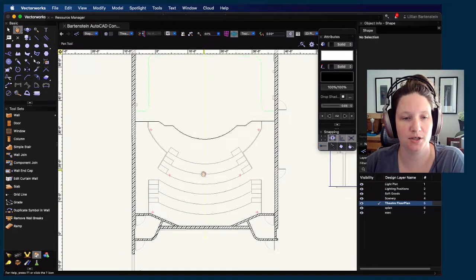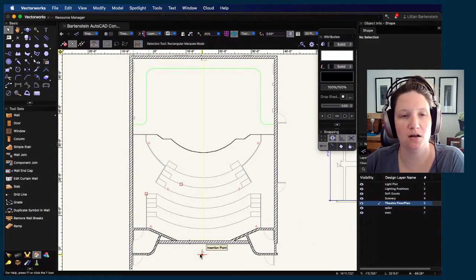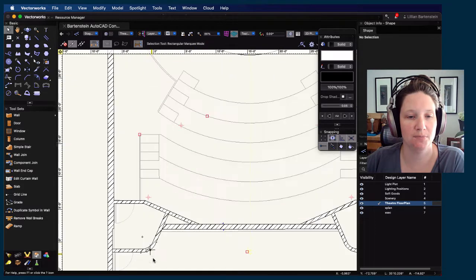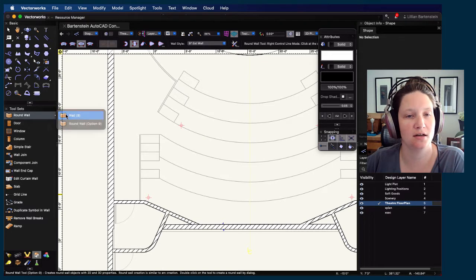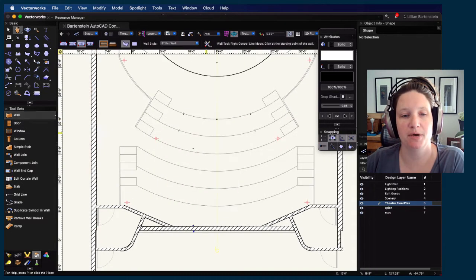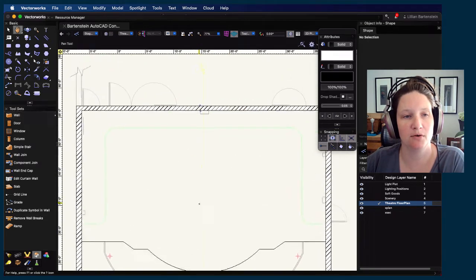Okay, so here we are. I've done all of my little walls. Pro tip, this little bit is the round wall tool, right? Just a quick note, mine is hiding right there under the wall tool, round wall. I chose this 3-point option to get that little curvy bit. So have fun with that if you feel like it. It is an optional step. But in any case, the rest of my walls are now all connected, going all the way around.